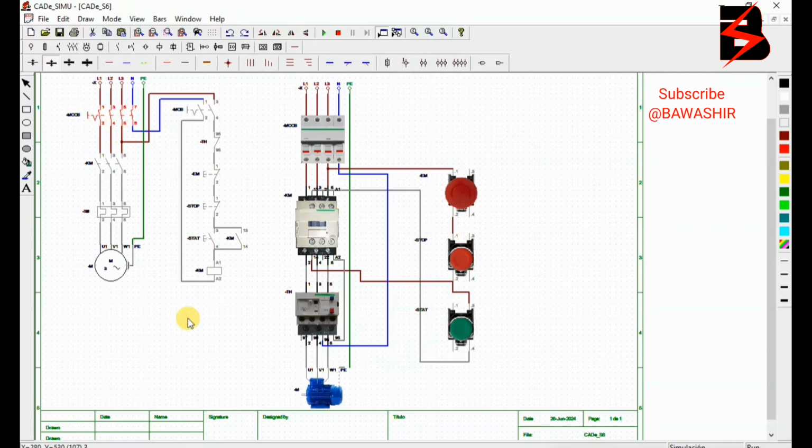Doesn't mean that when you're doing this wiring, maybe in the panel that's what happens, that maybe you'll have two different circuits, each being controlled all together. No, just this one is the inner view or the circuit view, but this is the real components. So when you turn on the control power, so when you press here start, you can see this way it is already running. When you press stop, it goes off. But unfortunately here, when I say start, this way it runs, but this way the overload, I think it is faulted. This line is not completing.